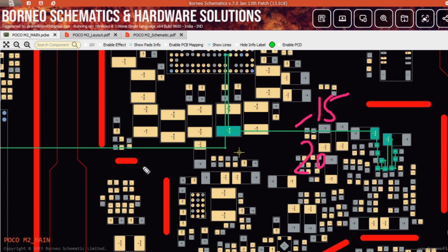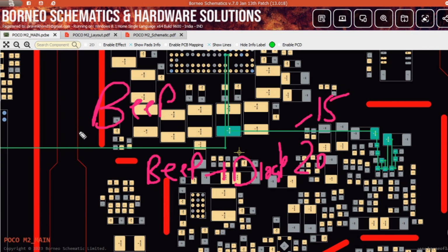Also, if they use a yellow multimeter or some kind of multimeter with a beep mode or diode mode attached, I mean to say combining your continuity mode and diode mode, with this kind of multimeter, when they test on this point in these capacitors, you will see your multimeter beep. So according to the multimeter, some technicians think this line is a short, right?